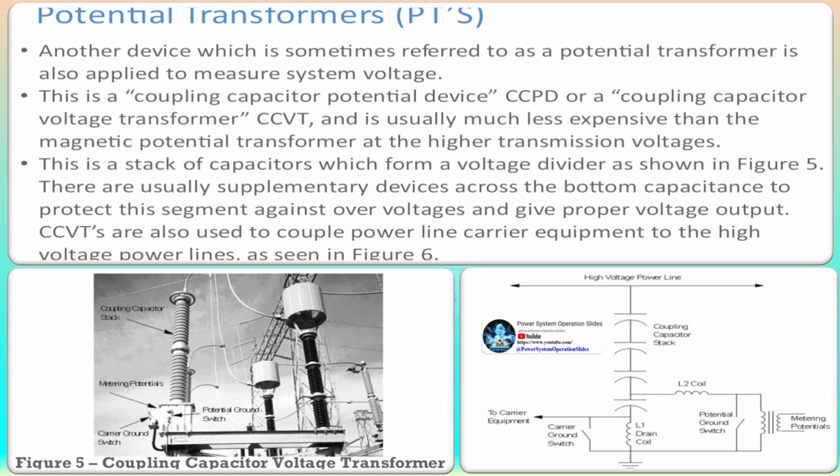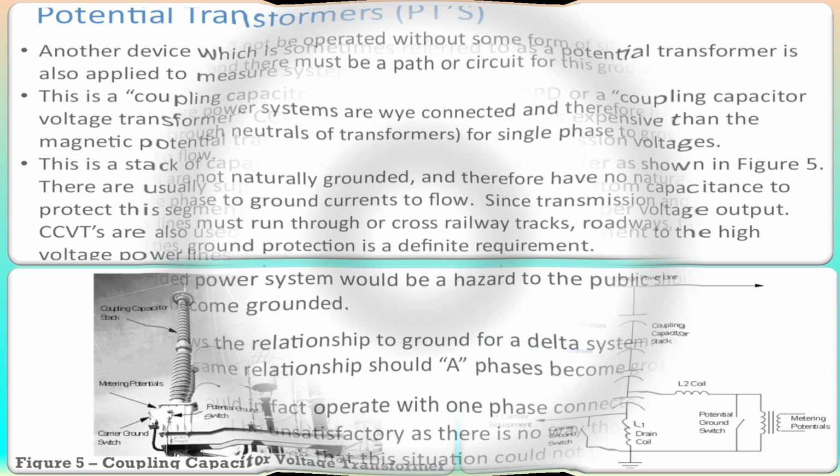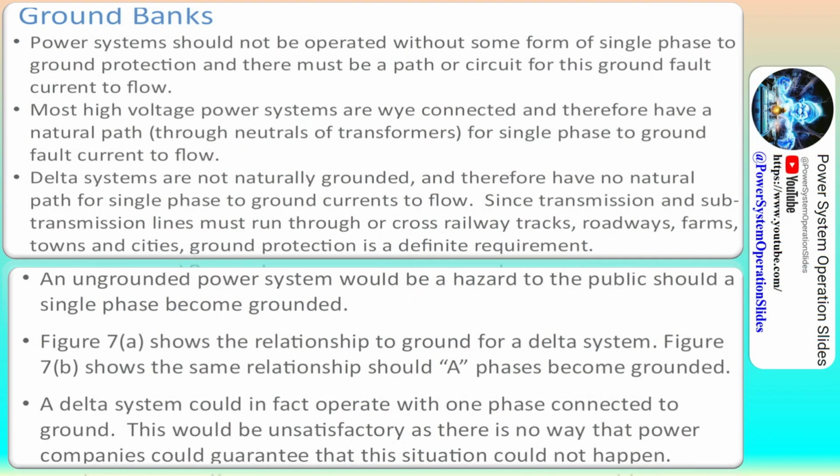If the PV inverter has an internal transformer with the grounded wye-delta configuration, a grounding reactor can be used instead by accessing the neutral point of the inverter transformer. Grounding transformers are used in power systems to provide a path to ground for any stray currents, and to provide a neutral point for grounding purposes. They are typically used in scenarios where the system neutral may not be available, or where the neutral of the system is not of sufficient capacity to carry fault current.